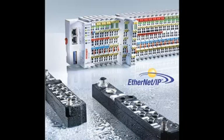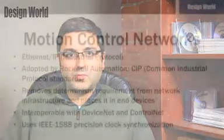EtherNet/IP with CIP Motion as the application layer removes the requirement for strict determinism from the network infrastructure and entrusts the end devices with the timing information necessary to handle the real-time control needs of the application. So this network can deliver the high-performance deterministic control required for closed-loop drive operation using standard unmodified Ethernet. CIP is also used by DeviceNet and ControlNet, so these networks are interoperable.